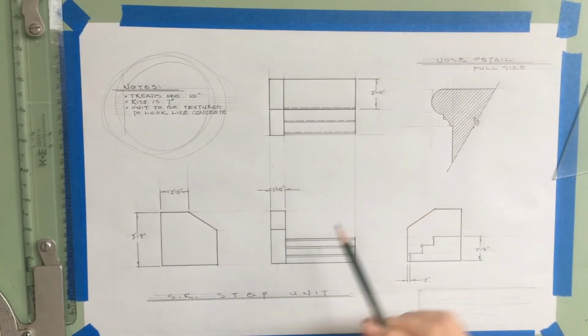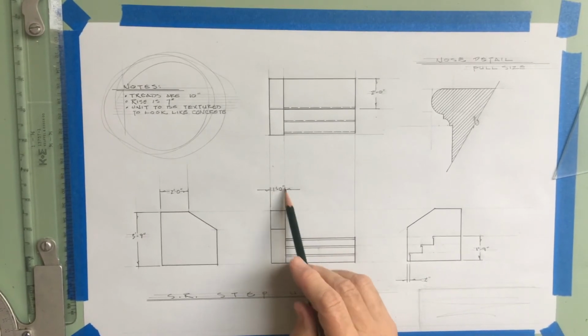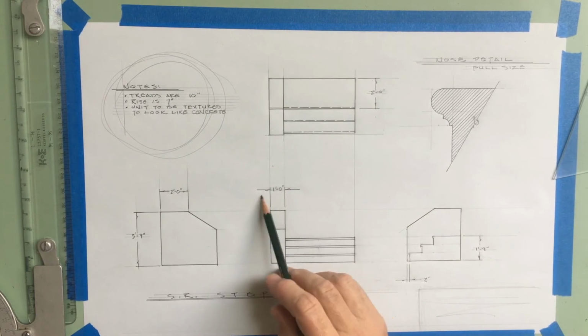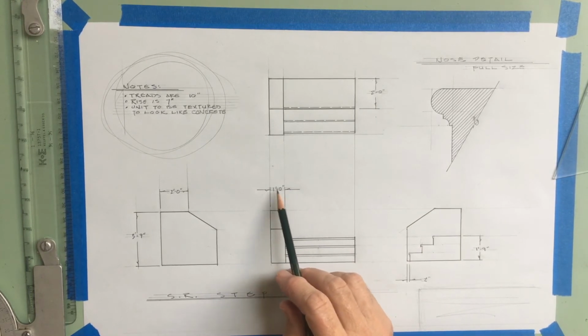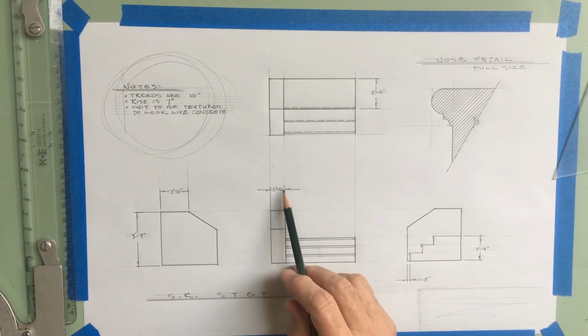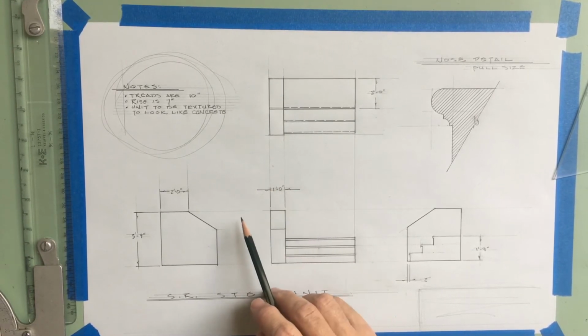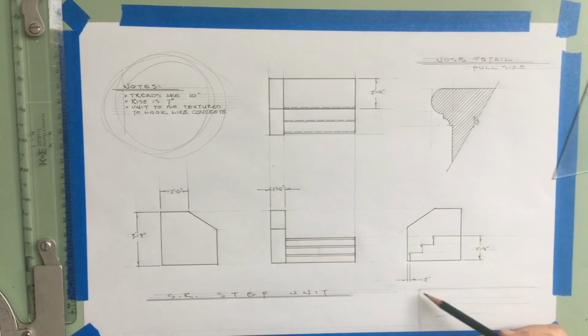Here's an interesting thing here. This was too small a space to have the dimension lines inside the extension lines and to have the dimension in there, so I just used the lines pointing into the space and put the dimension in. And here's an even more interesting one. This 2 inches is too small to have anything inside, so I've got the 2 lines pointed inside and the 2 inches outside. Those are little dimensioning tricks, and we're going to get a little deeper into that later in the term.